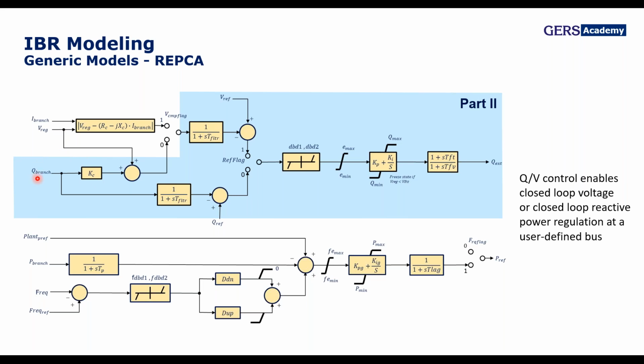So what you have here is a droop QB characteristic, and that follows the same kind of strategy. Most of the manufacturers include a droop branch, but there are others that don't allow droop compensation. But actually, it's based on the NERC recommendation that these parameters should be enabled.